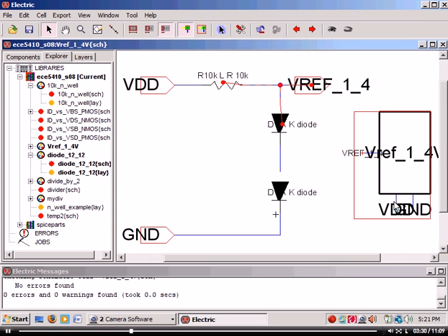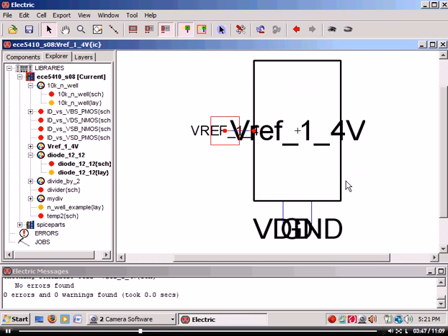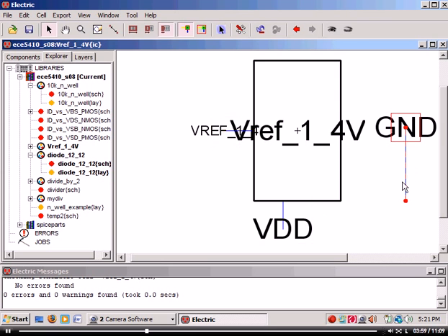Okay, so when you do your export, if you select input or output or power or ground, it will change the position on the box for you. Okay, but I didn't select those, so I'm going to go in and move them myself. And you can't rotate them because they're square. The wire you can move around, but if you try to rotate these, it doesn't make sense, if that makes sense. Okay, so I can move this around, I can pull it up, but I can't rotate this if I do a Control J because it's rotating a square.